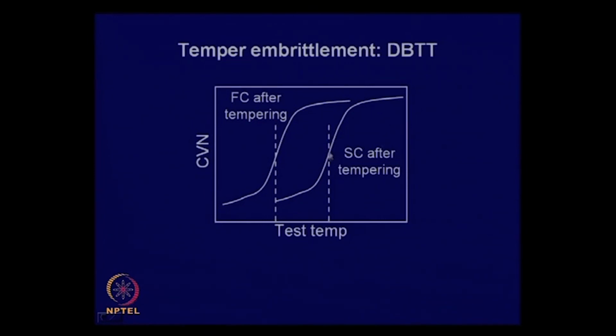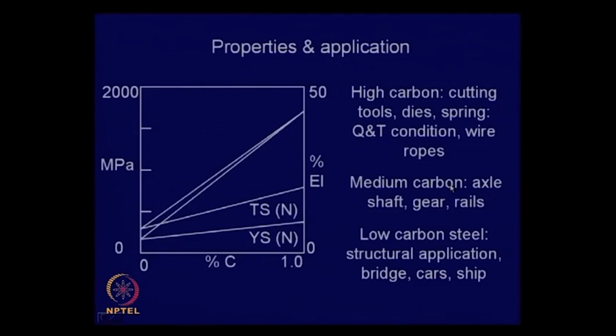Then in fact, you will find that service exposed materials have become brittle. So, therefore, you have to handle with care during any inspection. You should not hammer and cause a crack to initiate, and that can cause a severe problem. So, you have to be careful. You must know whether that steel is susceptible to such kind of embrittlement and take appropriate precautionary measures when you are performing any examination of any service exposed components.